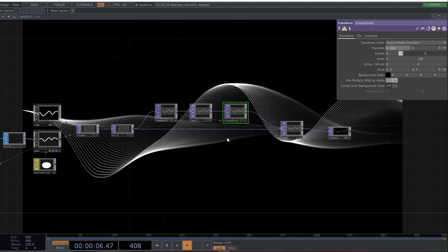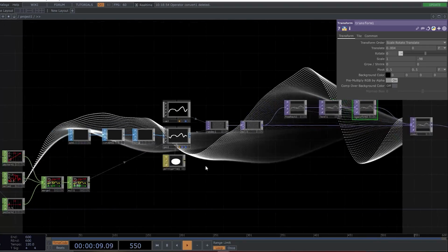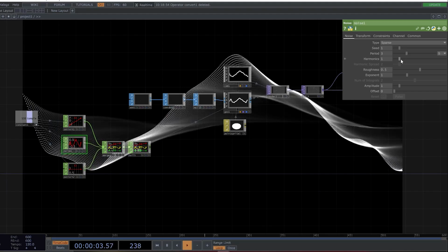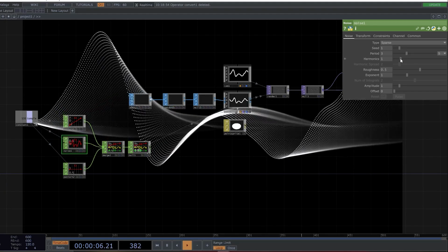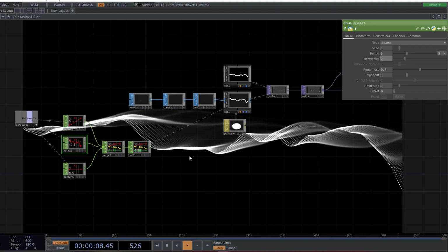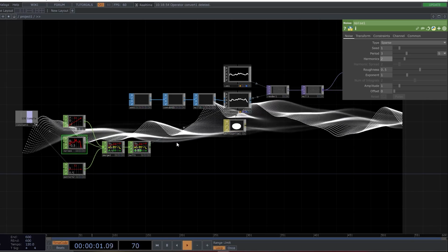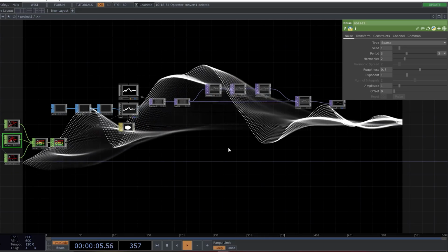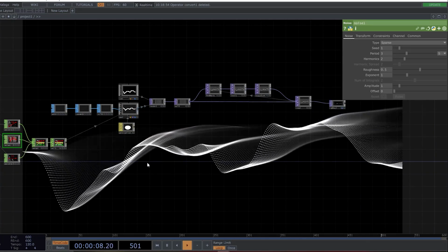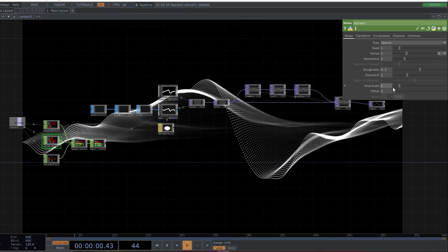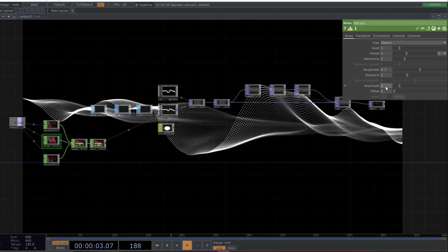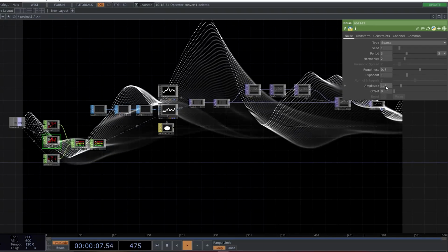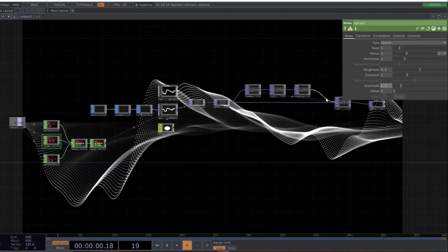The other thing that we can definitely do in this is we can have harmonics. So let's set the harmonics to 2, and we'll see some more waves coming up. And this gives a really fluid, much better look to our pattern that we want to create as a part of this tutorial. And you can also play around with the amplitude. So currently the amplitude is set to 1. Let's increase it to 1.5, and you'd see more jumps coming in.